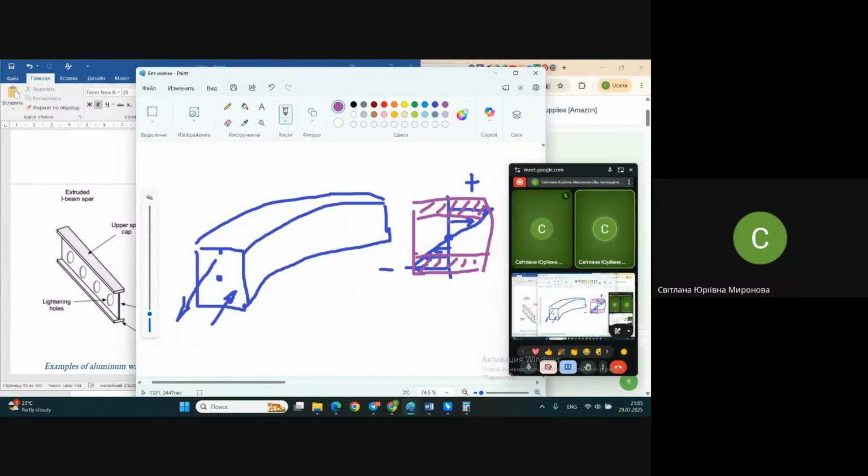And we have a lot of considerations, a lot of rules, details, tricks, on how to save weight in the structure of airplane design. One basic one, maybe, that you already get used to, or maybe you will get used to, is specific cross sections of structural elements.